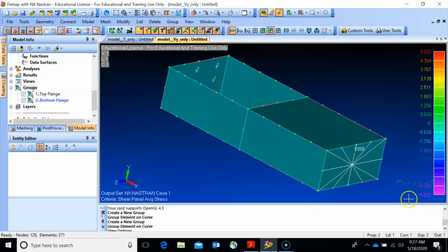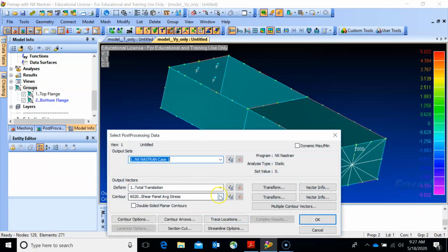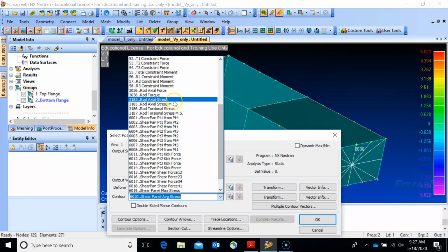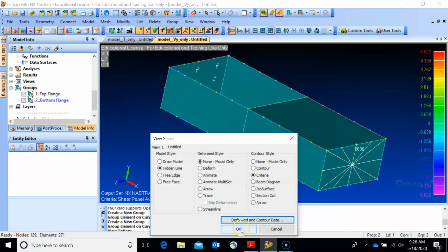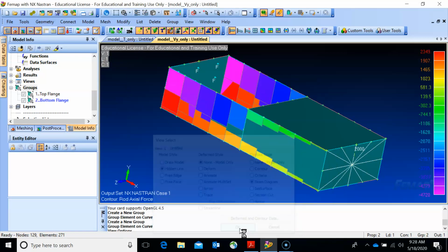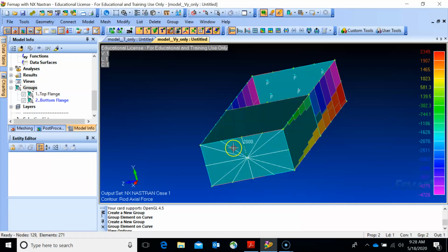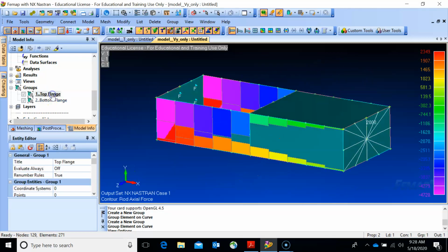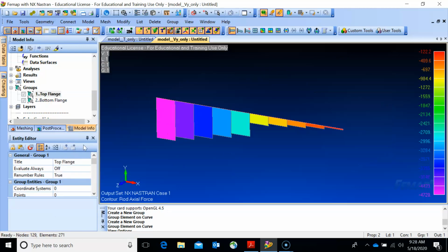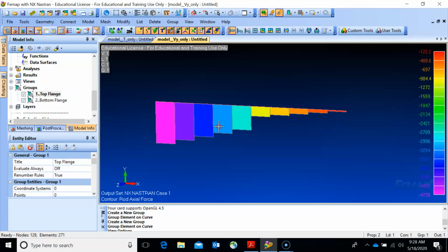No, sorry, F5. And we're going to look at the rod axial force. Okay. Beam diagram. Okay, so here gives you, oh, this one is a bit confusing, but if you come to the groups, right click, show active group, this will be the distribution for this one over here, which basically is minus this, about 4,720, but because the mesh size is not very fine, I think we had from 5,000 to 0.